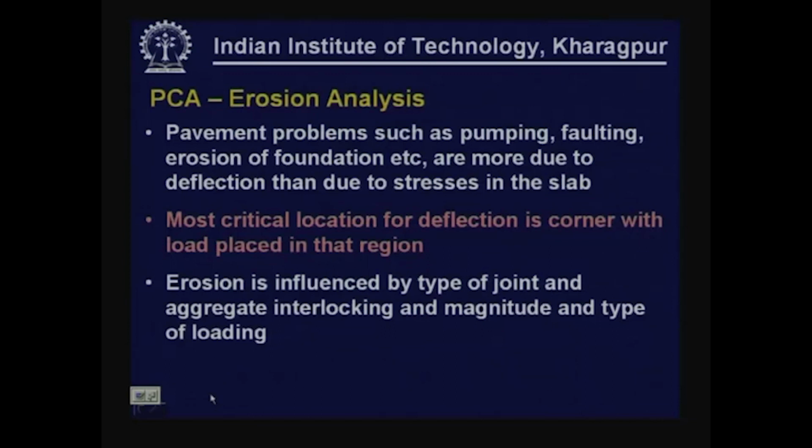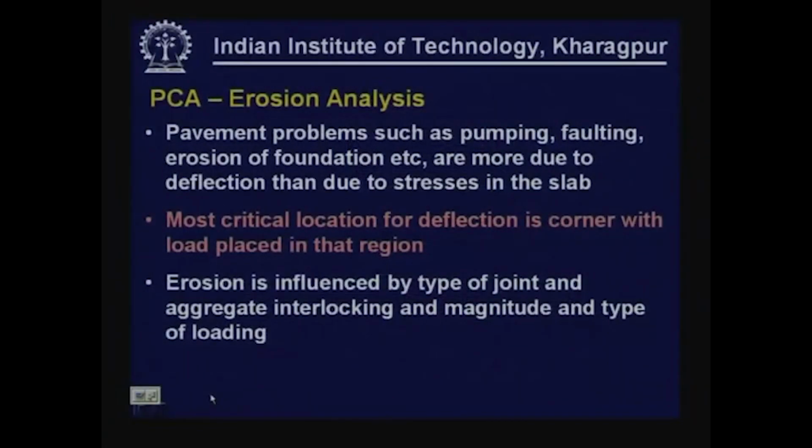Coming to erosion analysis, that is considered in PCA analysis, pavement problems such as pumping, faulting and erosion of foundation etc. are more due to the deflection than due to stresses in the slab. Deflection is the consideration that we have to be concerned about. If there are more deflections, there is going to be more pumping, more erosion, and more faulting problems are likely if the slabs deflect more. The most critical location for deflection obviously is a corner because of its discontinuity in two directions, that is when the load is placed in the corner region.